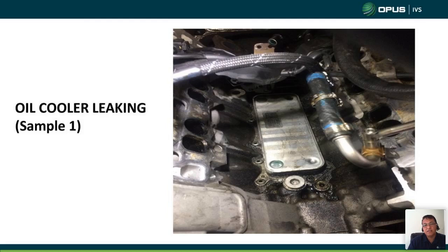If that is the case, 100% your oil cooler is leaking. Because I know most commonly they will think it is the rear main seal because it's on the bell housing area. So that's the first thing they normally do. So remove the gearbox, put a new seal. After putting it back, same issue.